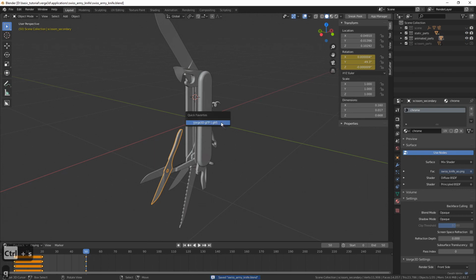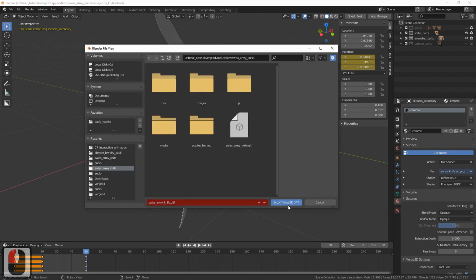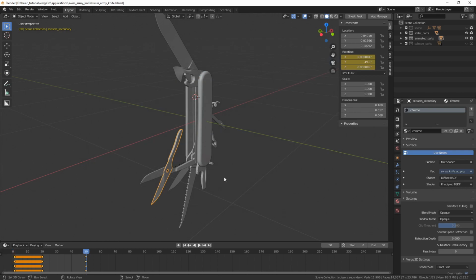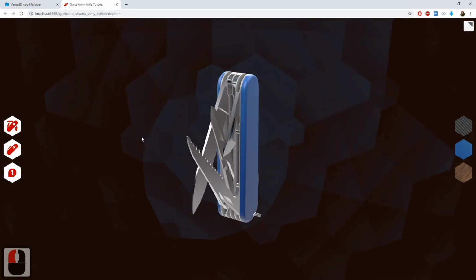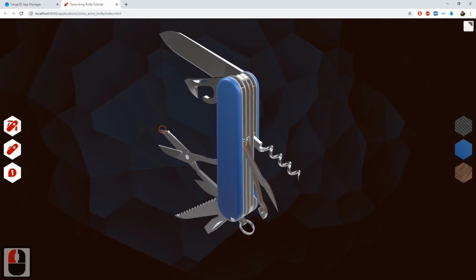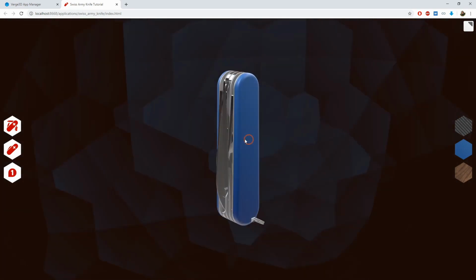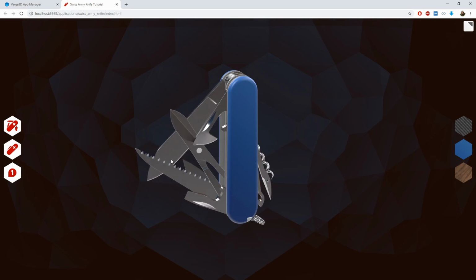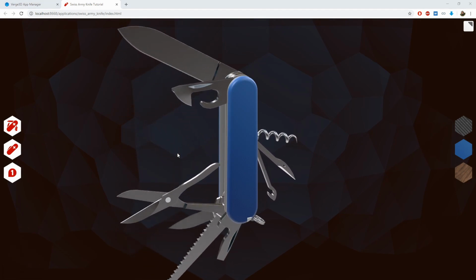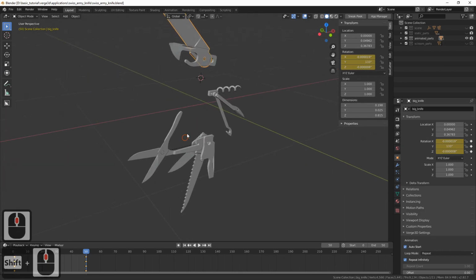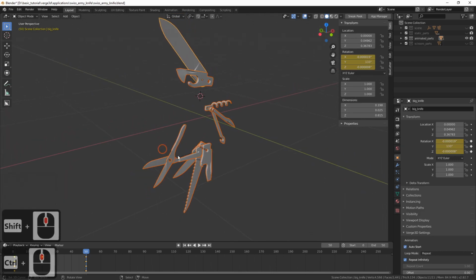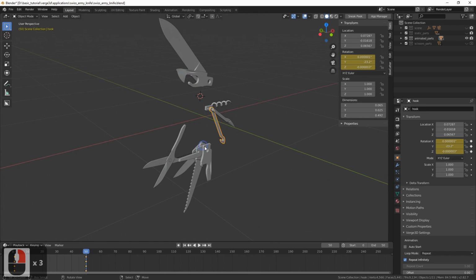Now let's export our animation to Verge3D. If we run our app, we can see animation is automatically played back right away. We don't want this to happen in our app. So let's get back to Blender. Select all animated parts and while holding the Alt key, uncheck Auto Start in Verge3D animation settings. This will uncheck this option for each of the selected objects.